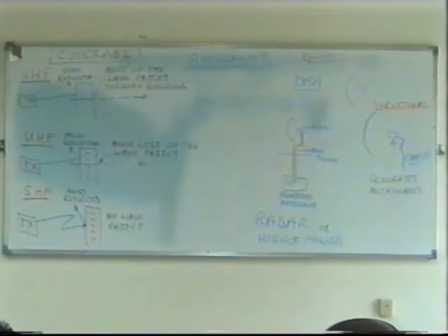What is the best coverage? In a word, VHF is the better coverage. For example, we've got now a VHF transmitter, an antenna on our roof, and somebody got in a car and drove right out to the hills and says, oh, we can receive it 60, 70 kilometers away. Great. But you couldn't receive it in the next street, you know. The point is, you've got to get coverage if you're in a city.